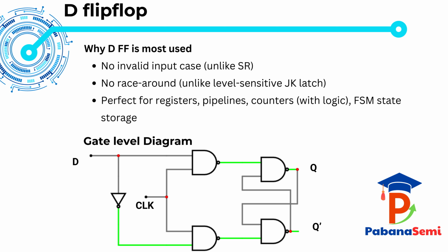That's why D flip-flops are perfect building blocks for real systems. They are used to build registers, pipeline stages, counters with some combinational logic, and also to store states in finite-state machines.